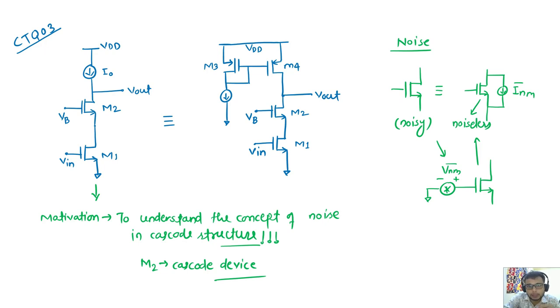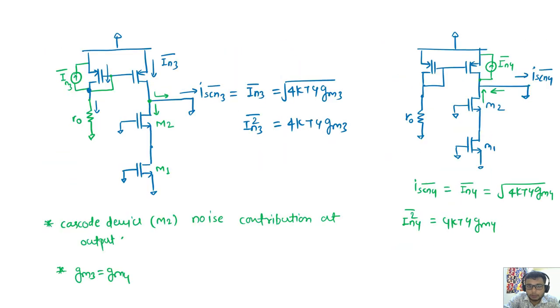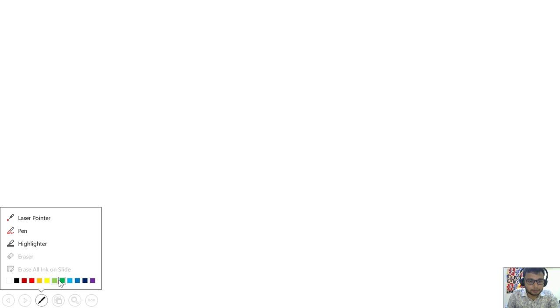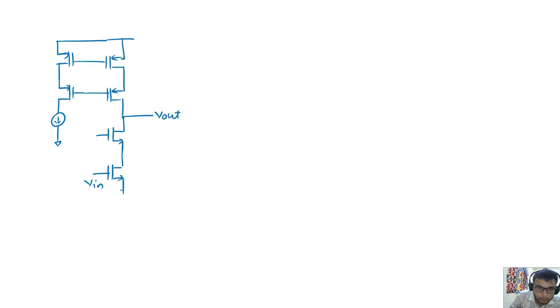Okay, if this cascode concept is extended to the PMOS, then you have to apply the same thing. I mean to say, if this cascode concept is extended to the upper side, for the PMOS device also, if I want to have some PMOS cascode as well, so if our structure is like this, VB2, and this is giving me VB3, anyway, I can bias it like this.